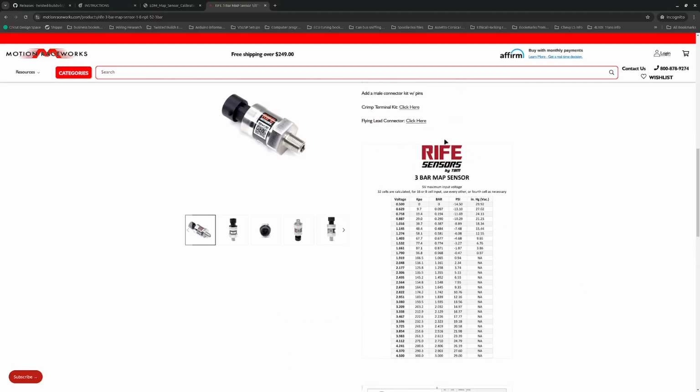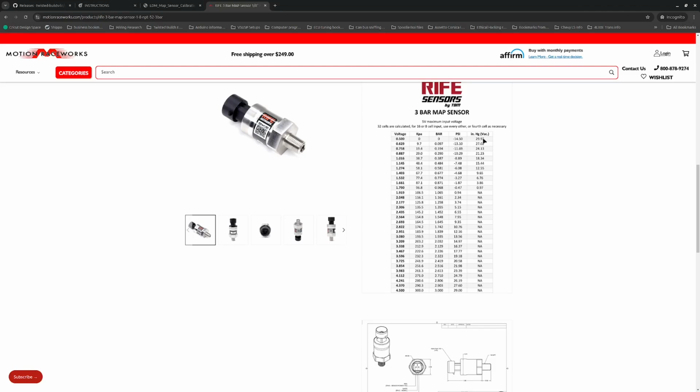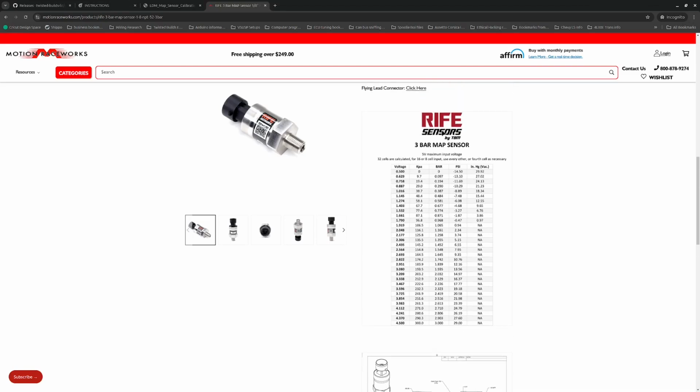Mega Squirt, stuff like that. We can put that graph voltage in and we'd be fine. However, if you wanted to hook this sensor up to a factory computer that used 0 to 5 volt, you don't have the data here to do that, right? We have the pressure gauge. We have the voltage from 0.5 volt to 4.5, but we need 0 and we need 5.